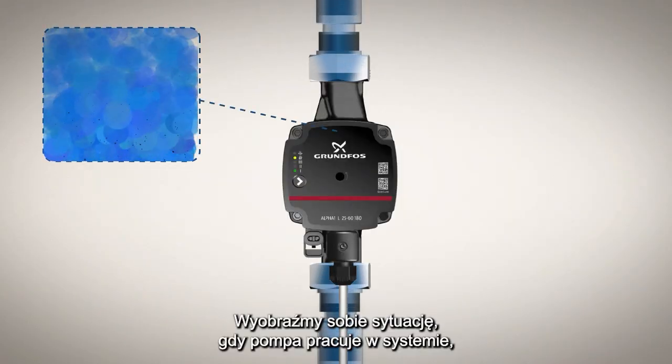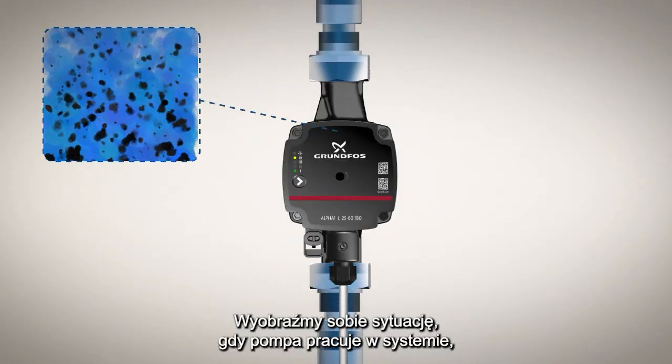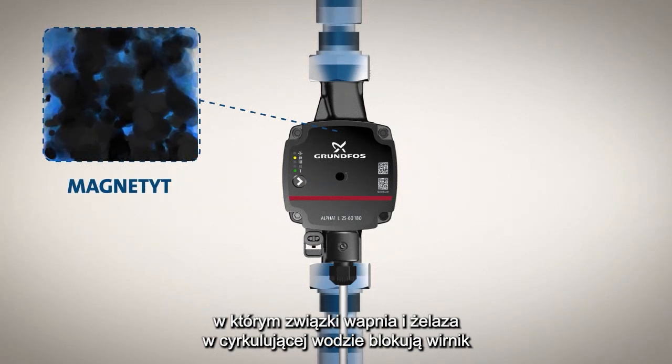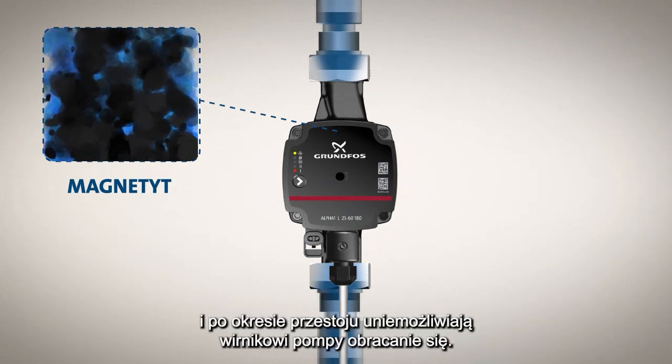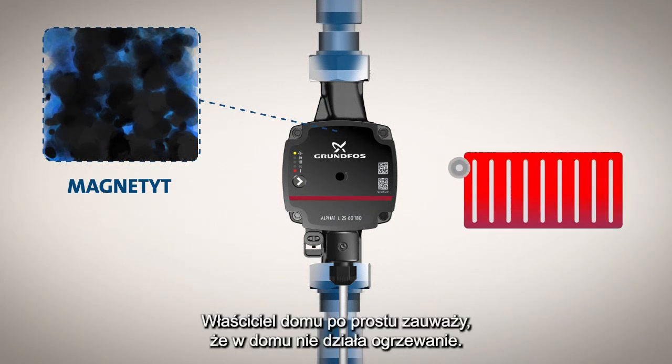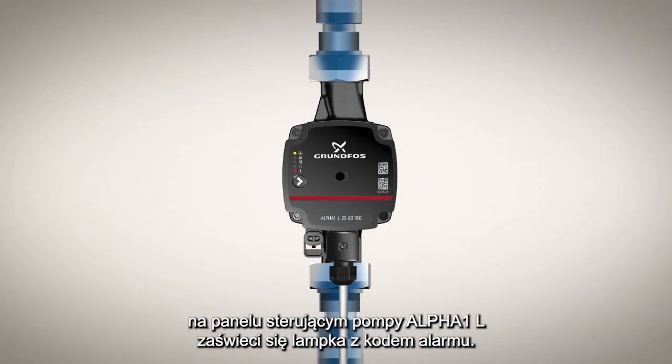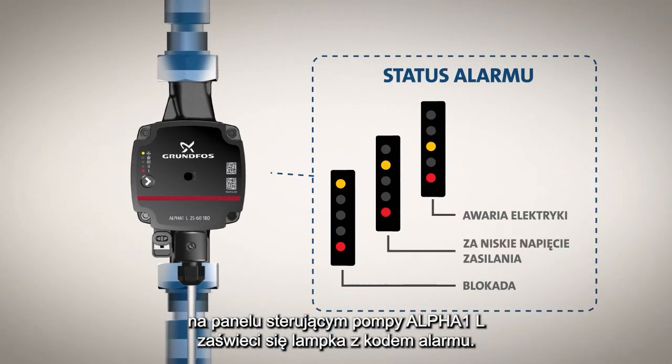Now, let's imagine a scenario where a pump operates in a system in which the content of magnetite in the circulated water blocks the rotor, preventing the pump from rotating after a standstill period. The homeowner will simply experience that no heat is delivered. In such an event, the interface of the Alpha 1L will light up with an alarm code.